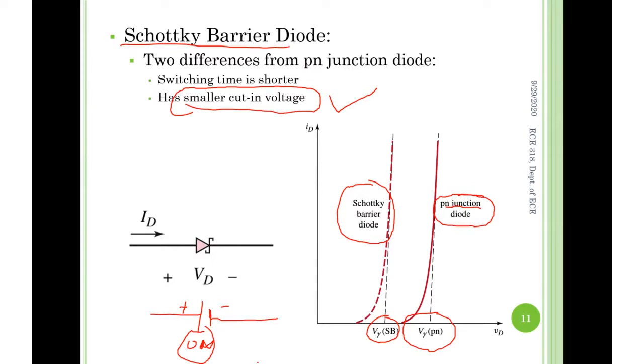Remember that for the half wave and the full wave diode rectifier, the DC output, you always need to what? Minus the V gamma. You always need to minus the V gamma. Why? Because of the voltage drop. This is the voltage drop through the diode. We don't like it. No reason to like it. It doesn't make sense. Why would you want to lose the source voltage? No, we don't. So this is the reason why.